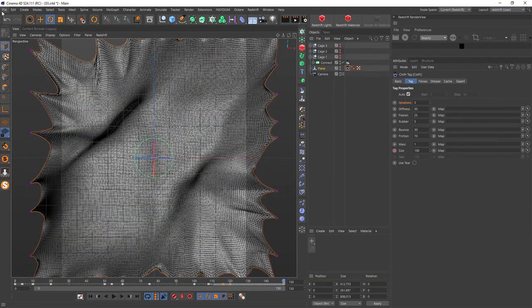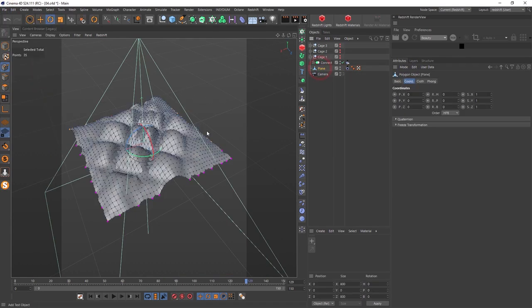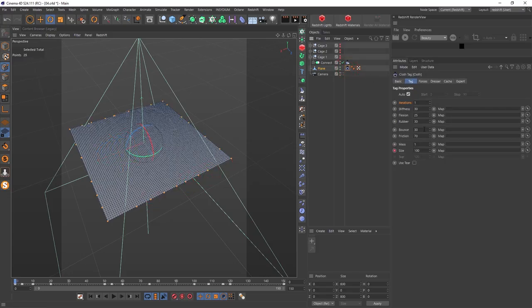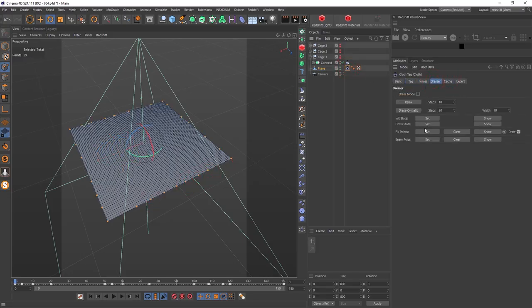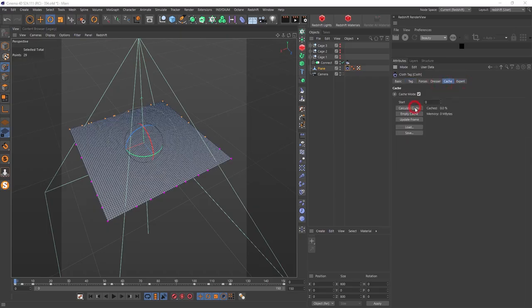Also, we'll make one more test. So I save this thing and open point 2 file, save incremental to point 4, and I would like to add only one subdivision. Deselect all, one subdivision, plane, reselect our corner and side points, going to cache, fix points, forces, tag, increase iteration to 3, decrease rubber to 5, maybe stiffness to 40, and let's calculate this cache.